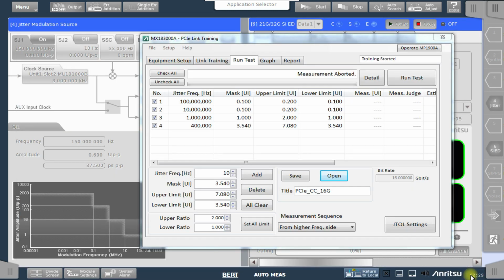Another very important analysis feature is the jitter tolerance test. A similar concept to the matrix scan shown before, we measure a bit error rate against two parameters, jitter frequency and jitter amplitude. Many standards define the measurement ranges, like PCI Express Gen 4 in our example.